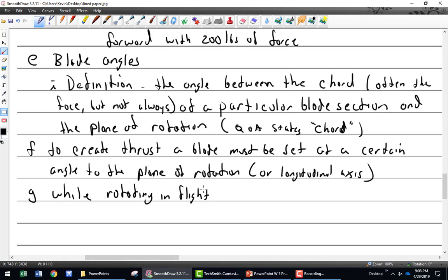If I'm stopped and my feet are on the brakes and the propeller is going around just like this, it's really easy to figure the angle of attack. It's coming around, and the air is not moving in any way, shape, or form. So the angle of attack is exactly where the propeller is coming down and striking the air. Follow? But now if I go forward, I have it striking the air, coming down, plus whatever forward momentum I have. Those two things now work together, harmoniously, to create problems.